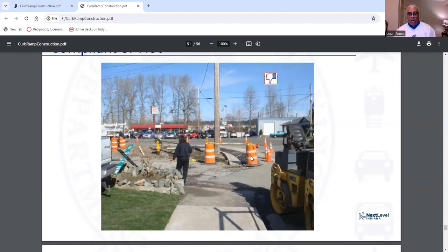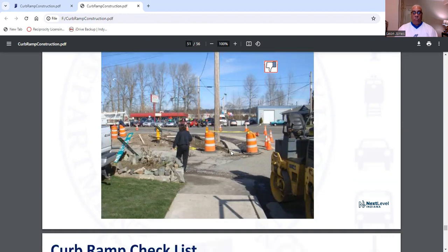And if nobody's around here, this should be roped or taped off. That's one thing that I will look at when it comes to inspection. If there's nobody working in that area, it should have some yellow safety tape, because you want to secure the area to make sure it's safe for pedestrians, or close the area.